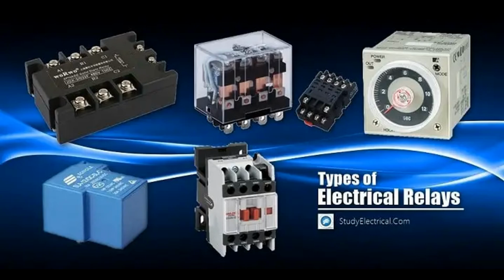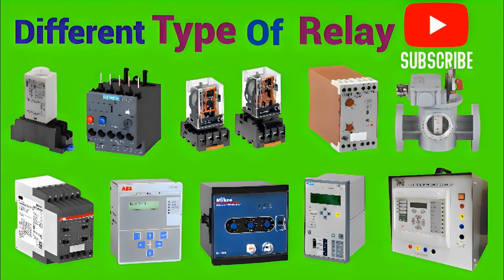Short circuit protection. Relays play a role in protecting circuits against short circuits, where an unintended connection occurs between 2 points of differing electrical potential, resulting in a sudden surge of current. Short circuit relays detect the abnormal current flow caused by a short circuit and quickly disconnect the affected circuit to prevent further damage. They help isolate the faulted section of the circuit and minimize the risk of fire or equipment damage.